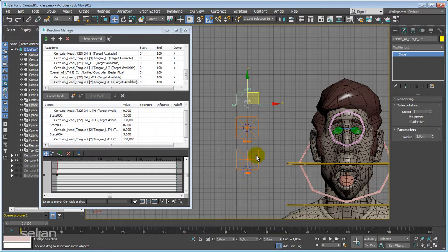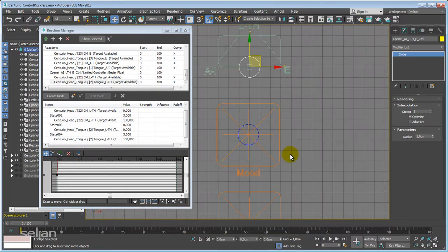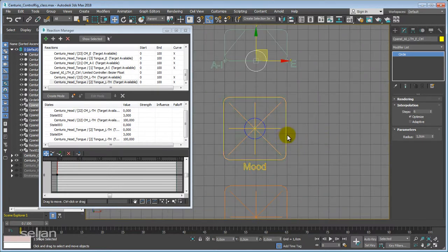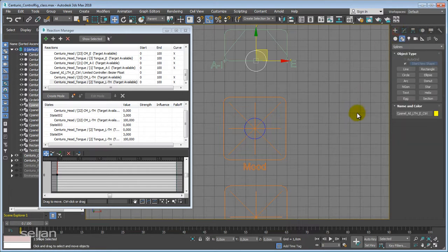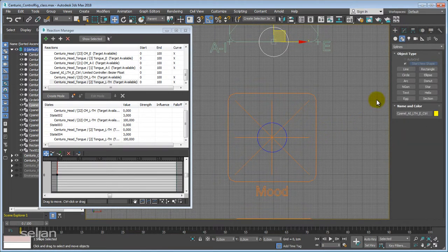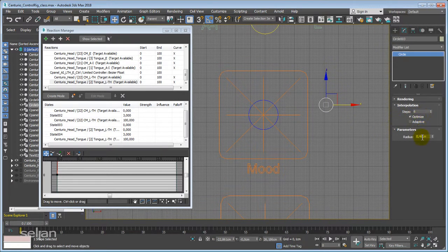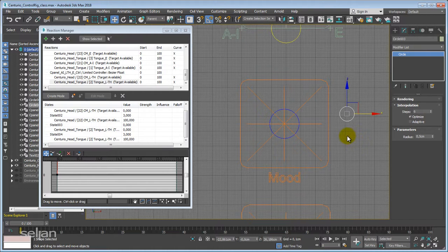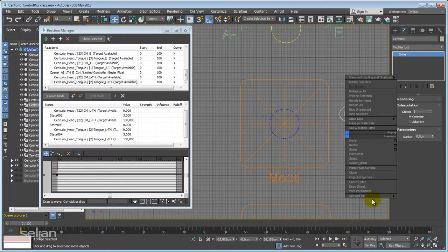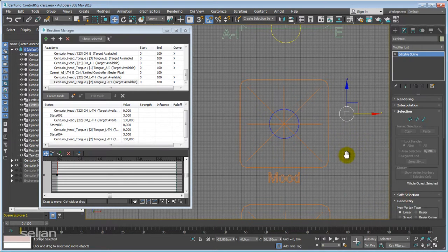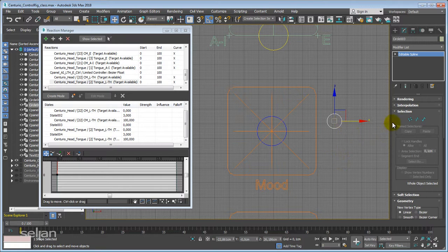What you can do is actually create a joystick in a joystick. It sounds weird, but it's not that weird. So what we will do, we will create a smaller circle, about 0.5, so it's 1 centimeter in diameter, and now we can convert it into an Edit Spline.